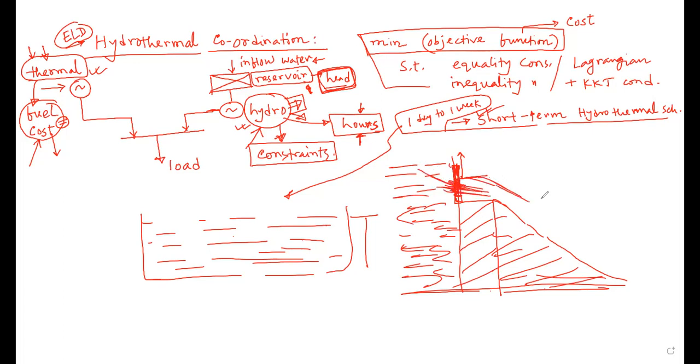And of course, there are components like the penstock and inlet valve, and through the penstock the water will ultimately go to another channel, another control valve. By closing and opening this control valve, you can control the flow of water through the turbine blades.